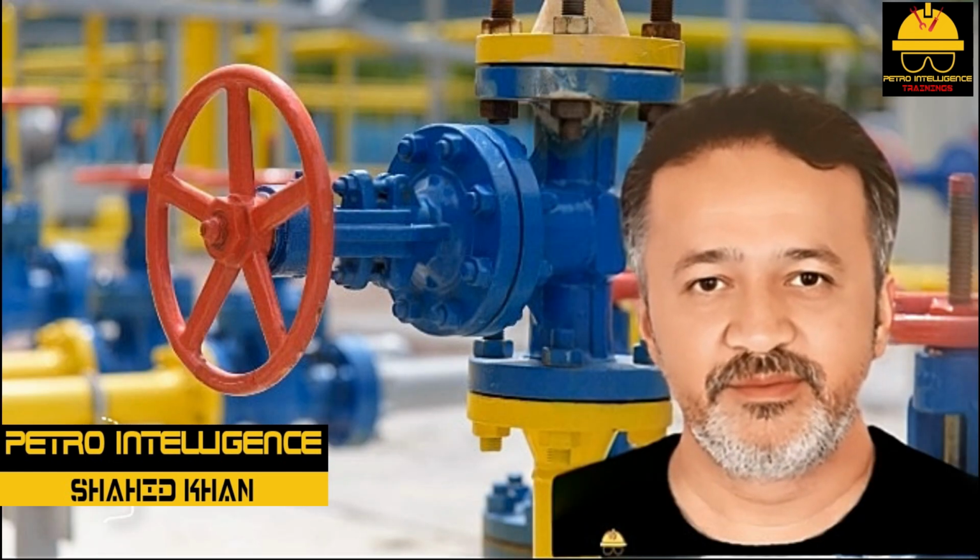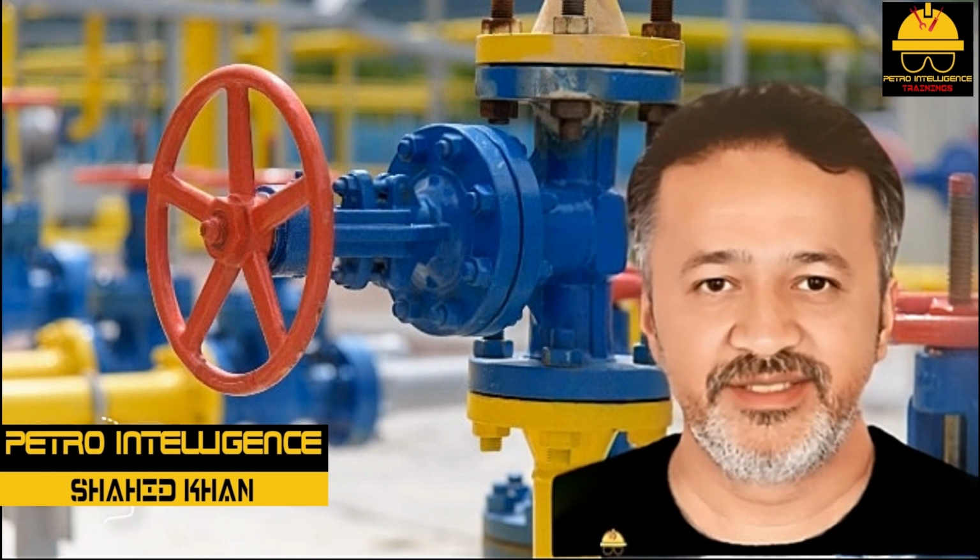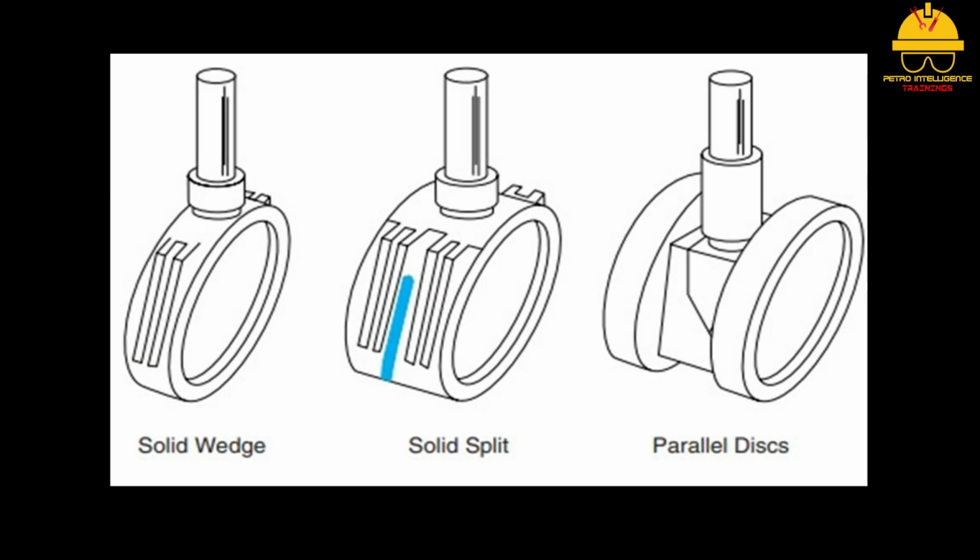Common gates. The gate on a gate valve comes in a variety of shapes and sizes. The most common designs include the solid wedge, solid split gate, and parallel discs as shown in picture. The solid wedge gate forms a positive seal when the solid metal gate slips into the seat. A set of guides keeps the disc aligned.